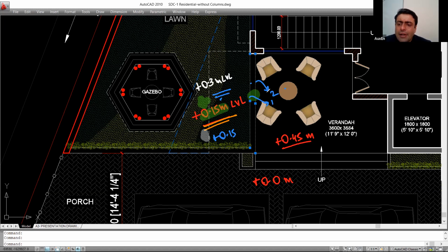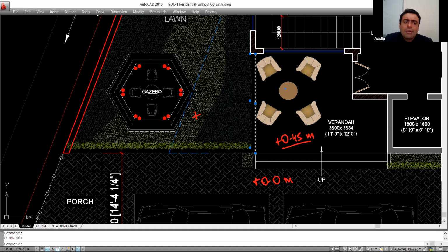It's very rare to see them 2 steps below the plinth. I'm talking from my personal experience of whatever I have seen till now. Therefore, the reason for this confusion. As per this drawing, it is showing 2 lines, so 2 lines should indicate 2 risers. But from our general experience, I'm telling you this. So this thing we need to clarify. I will do that clarification and I will tell you.